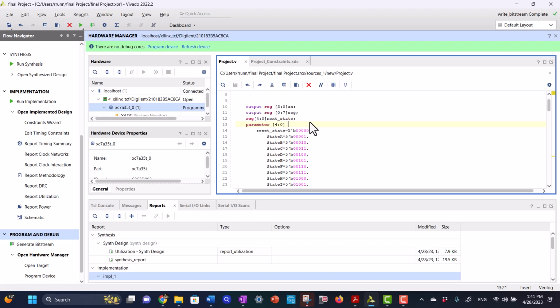This is the logic of everything. How do you figure out what the next state is? And so you need to have a variable name for that, and you'll do that in an always block. So that's going to be listed up here when you do your inputs and outputs and your parameters.